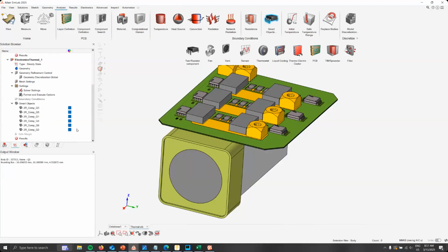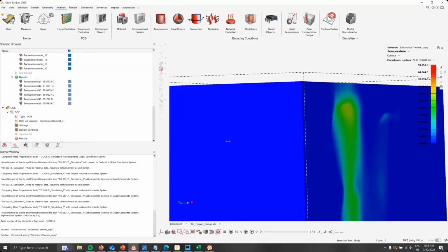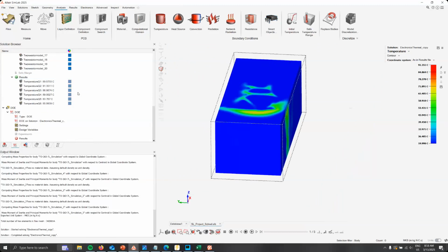I've seen situations where you've had a super complicated CFD model that takes maybe 24 hours to solve, and then when you use the initial conditions, it's solved in like half an hour or so. Not saying that this model takes that long to solve, but that's the kind of speed up you can see when you use the initial condition setup.